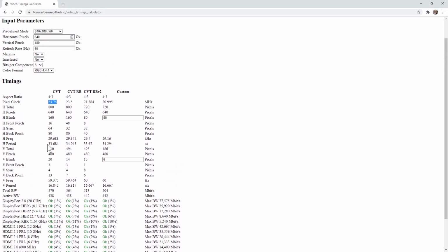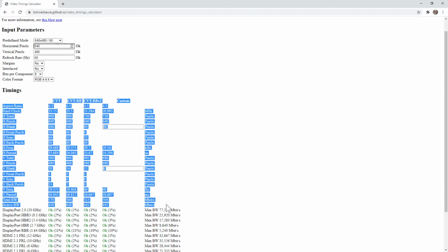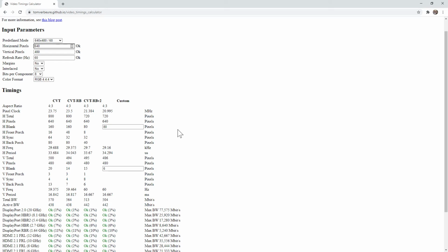What I actually like about this timing calculator is not this, which is just a lookup table of this part here. For a given resolution spec, here is the size of horizontal pixels. Here's how many rows there are, or here's the size of each row. Here's the number of rows that we have here. Here's the size of those individual synchronization pulses to be able to generate a valid signal at that resolution.